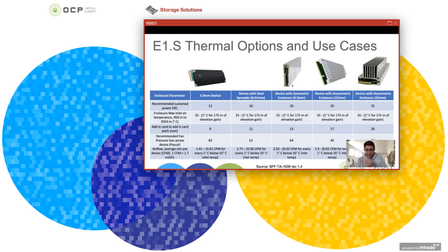It stands just like this as it mates into a 1U chassis. And the current specification calls for up to 20 watts, which is a really interesting point. So for mainstream SSDs in the next few years, 2 and 4 and 8 terabytes NVMe SSDs, this 20 watts is actually a pretty good power range for what PCIe Gen 4 devices will be able to deliver.